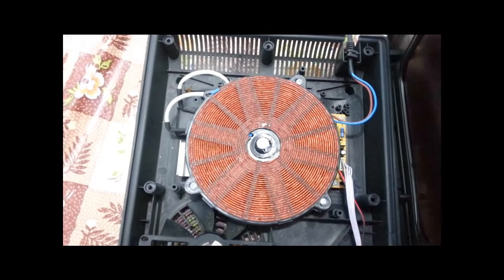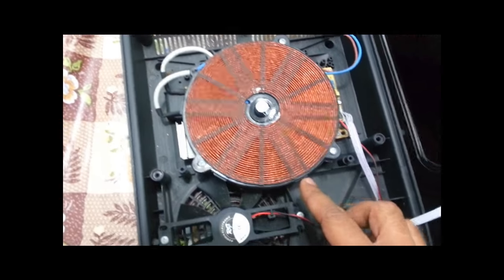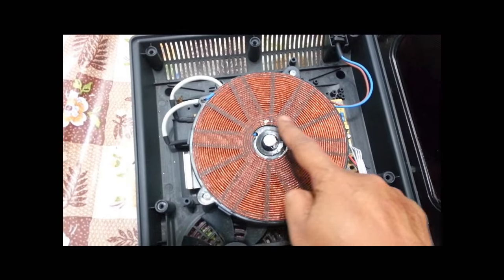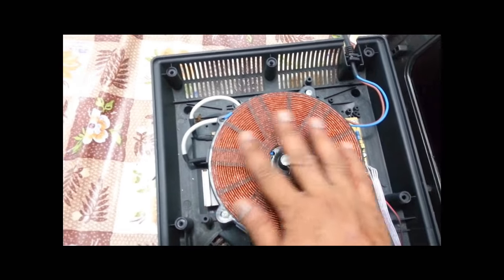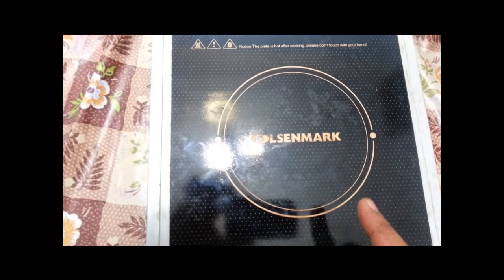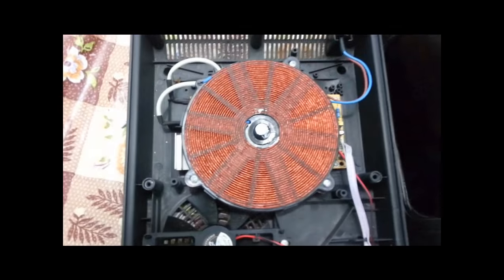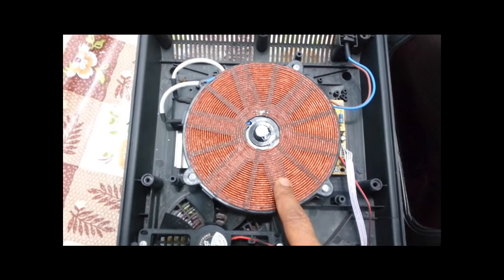and we are giving the electrical supply through these two wires. So when an alternating current is passed through this coil, it produces a varying magnetic field. A high variation of magnetic field is created in this area, and we have to keep the vessel just above it, on this circle. The vessel kept on the surface should be a metallic one. So eddy current will be induced in the metallic vessel itself, and it will get heated up, and that heat energy we can use for cooking the food. So the main working part of the induction cooker is the coil, which provides a varying magnetic field.